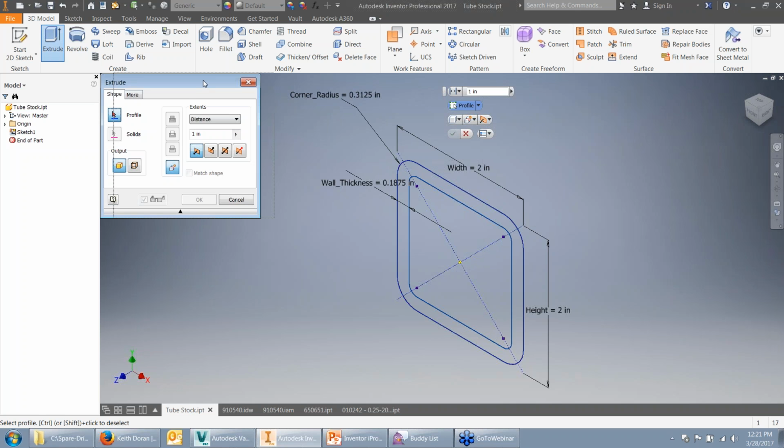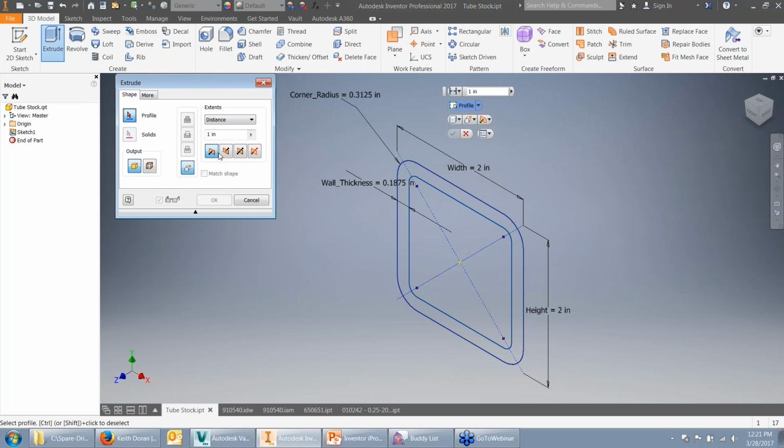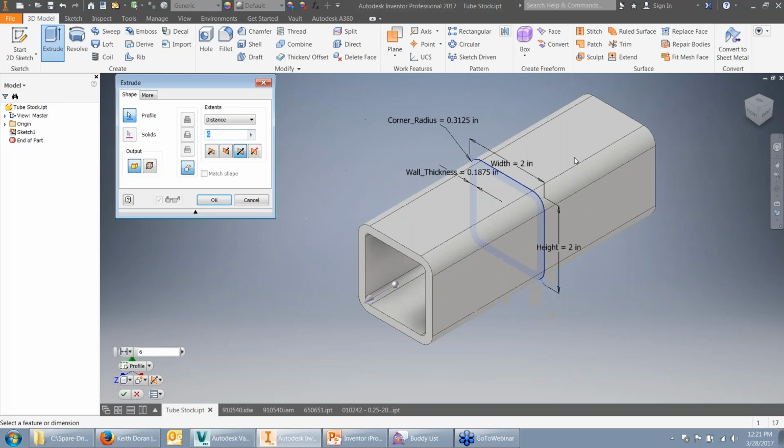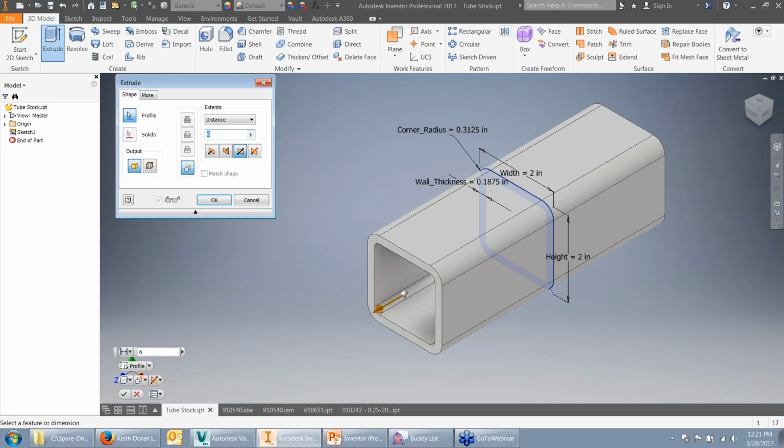So when I use the extrude command, comes up and there's my 1 inch that it's going to extrude, and I'll go ahead and say 6 inches on that profile, make it asymmetric. And whether it's 6 inches, 2 feet, 3 feet, whatever you plug in your value, this is going to create another dimension in that parameter. It'll be D4, dimension 4. There's also going to be a dimension 5 created. Even though you don't see it here, that dimension 5 is going to be the taper angle of the extrusion.